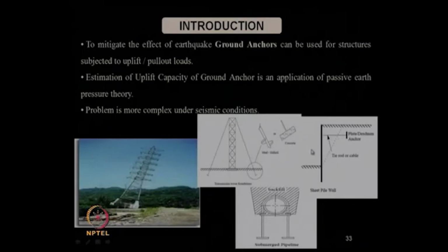Another application, as we know, is the sheet pile wall design, for anchored sheet piles. To reduce the excessive lateral movement of the sheet pile, we provide plate anchors like this, right. So that the sheet pile is tied in such a way that it does not deflect excessively. Okay.